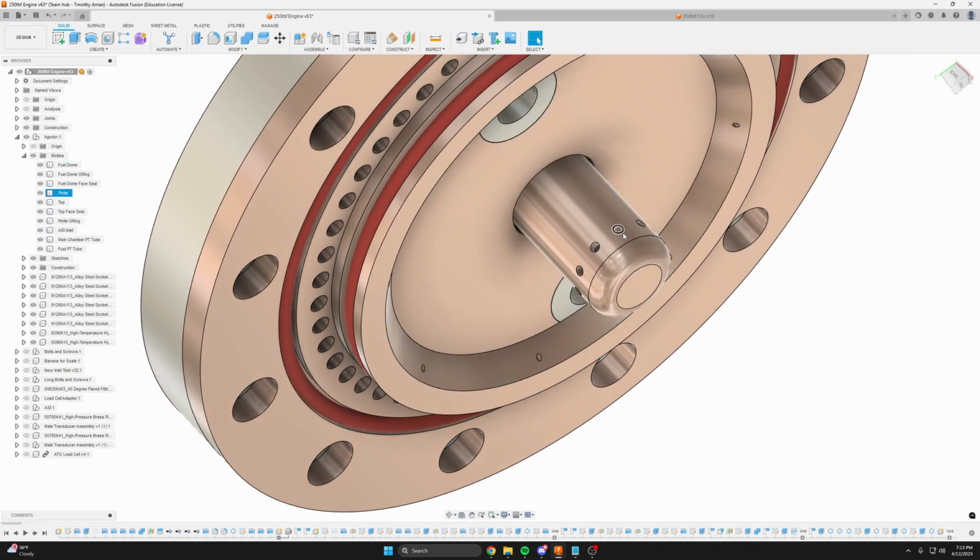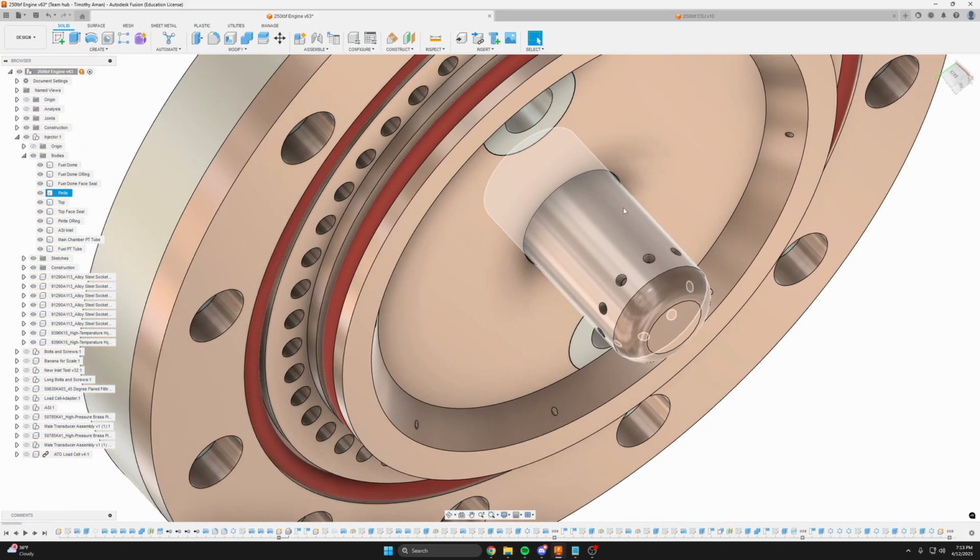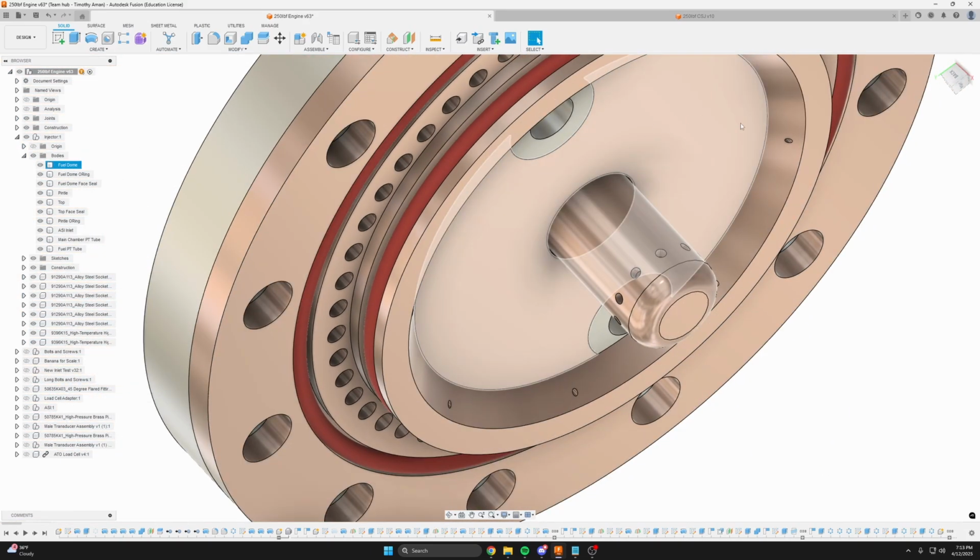So instead of having it shoot out, it's just shooting straight down, and there's an annulus gap for the other propellant, and you probably have multiple shear injector elements.